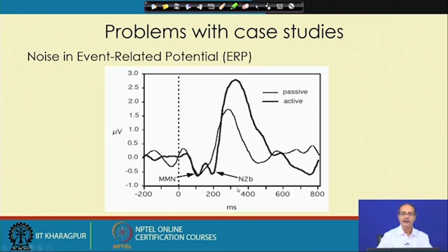If we think of an ECG signal, in case of ECG, we can take multiple cycles of the ECG, and we can add them up to make the synchronous averaging possible. So, in that way we need to have multiple signals; without that we cannot make use of this synchronous averaging.